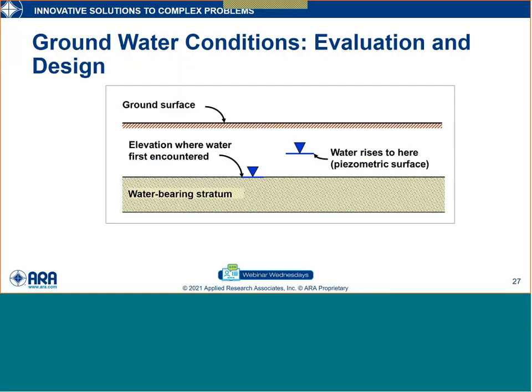Groundwater. We're almost near the end of this little segue. Groundwater is often a topic overlooked. We think that when we drill an exploration and we encounter the water table, that it's static and it goes down to infinity. If you think the geotechnical material environment is complex, you haven't lived until you've looked at hydrogeology and the subsurface environment at some sites. It can be extremely complex, often overlooked in practice, often overlooked in terms of time changes, both in a calendar year or through multiple years through the duration of a project, looking at, for example, extreme events.